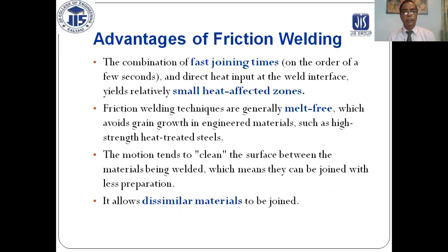Advantages of friction welding. The combination of fast joining times, on the order of a few seconds, and direct heat input at the weld interface yields a relatively small heat affected joint. Friction welding technique is generally melt free, which avoids grain growth in engineered material such as high strength heat treated steel.